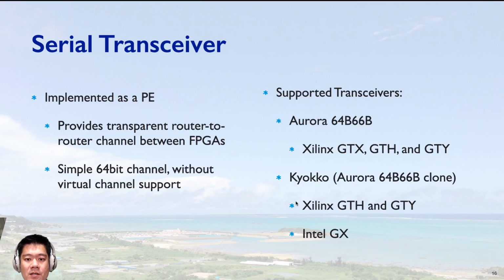The transceivers are controlled by Aurora cores from Xilinx or its OpenFC clone called Kyokko. With Kyokko, Intel FPGAs are also supported, and both Intel and Xilinx FPGAs can communicate with each other.